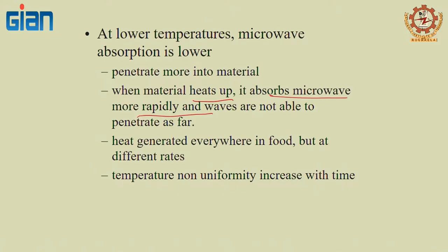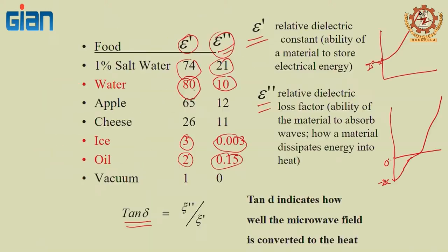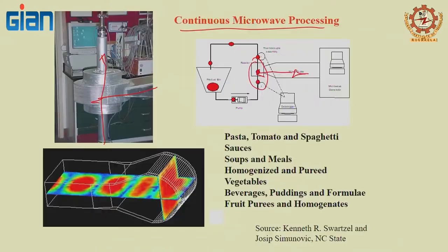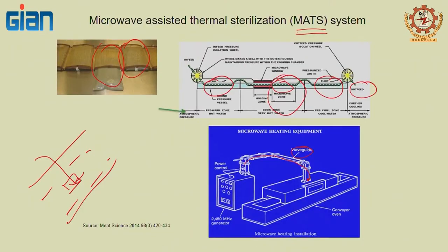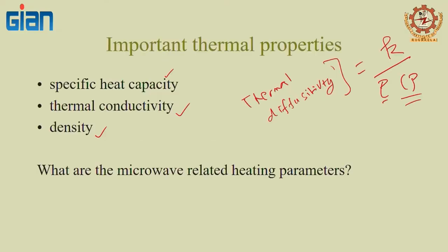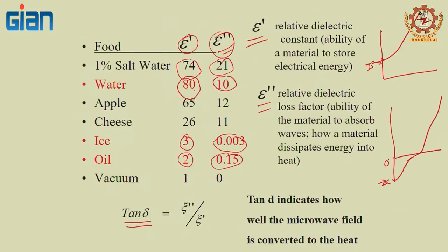So that's the reason why, to avoid that non-uniform heating, in the case of the Washington design, they just added water in the mix, so that they are heating the pouches in the presence of water. So you not only heat the product with microwave directly, but you are also using the water as a supplemental heating, so that you maintain certain uniformity of the product.